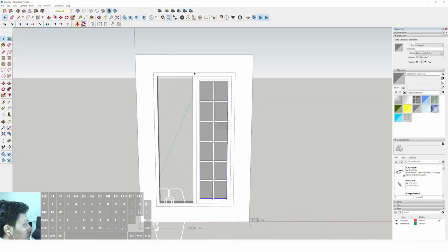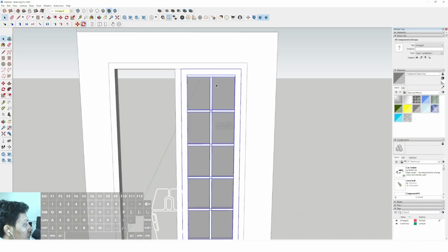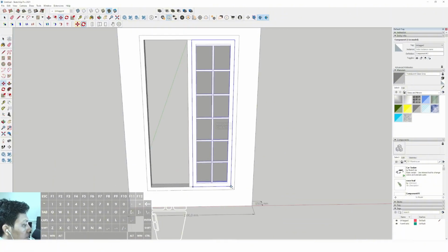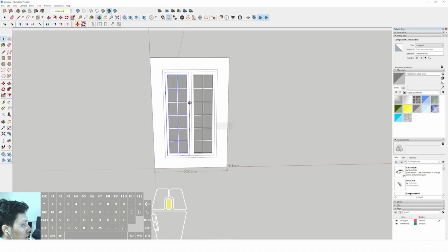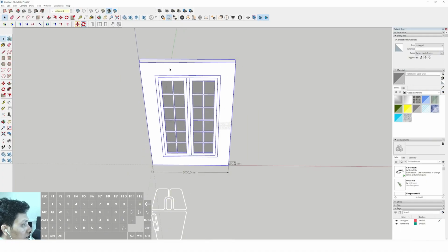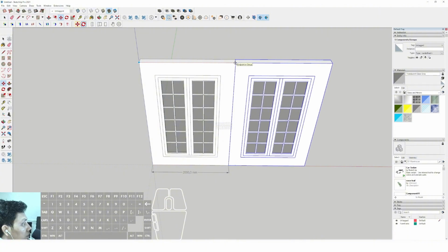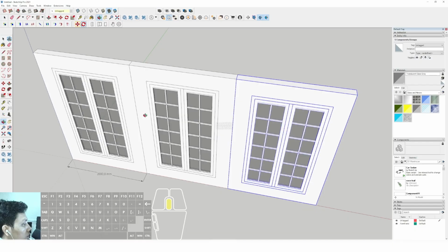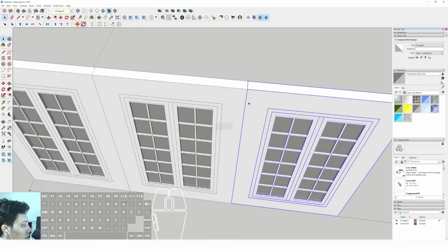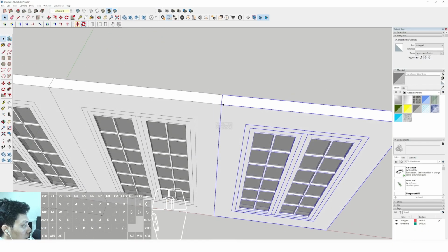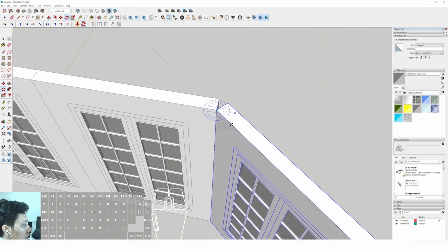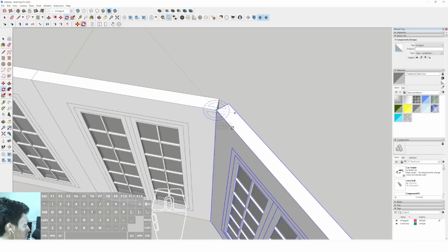Okay, and we can select all this window leaf component and also make component. Just create and select move, place to the position. Okay, then we can select the element, click duplicate and duplicate with 2 times. Select Q to rotate, click from the corner, then we can type 45